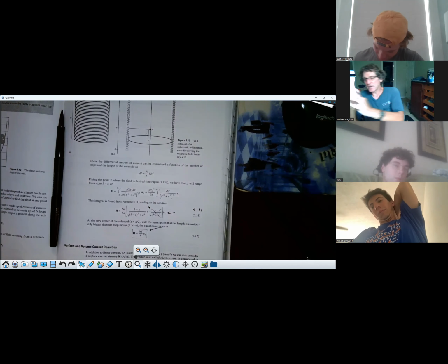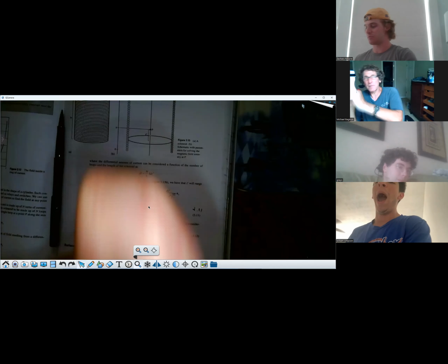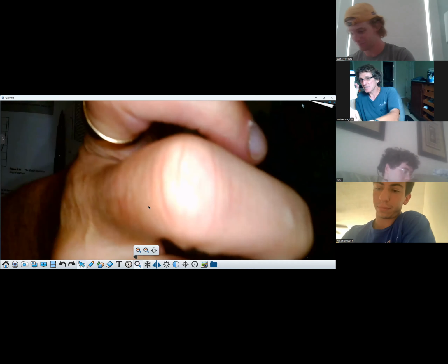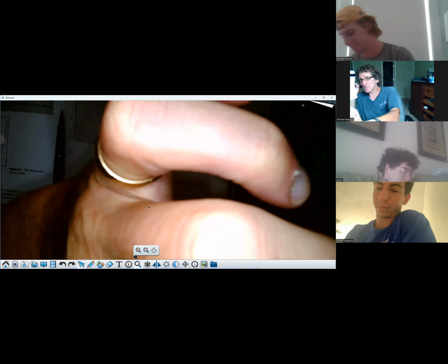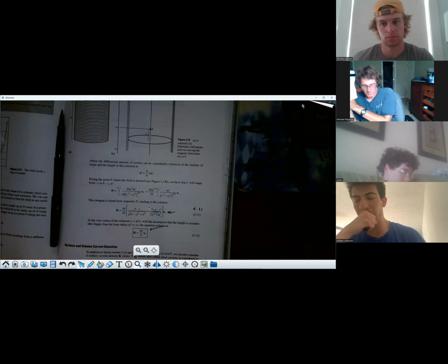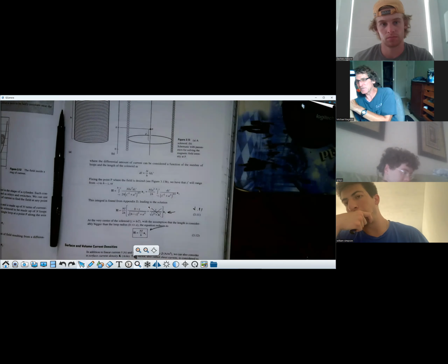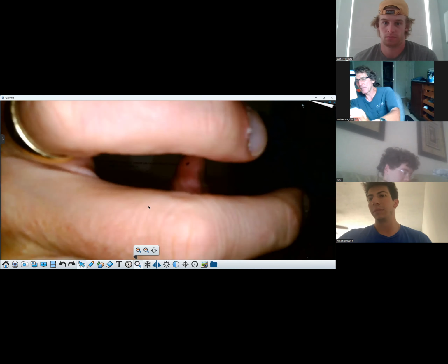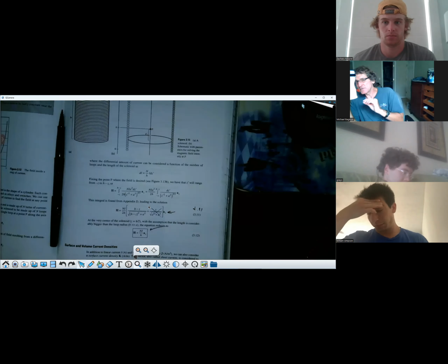So if you just think of something about the size of the core on a roll of toilet paper, or maybe paper towels. So you got something maybe a foot long, and you wind it with maybe 1,000 turns, maybe 10,000 turns of wire. And then you put current through it. It's going to have a magnetic field that's given by this at the center, and it's got a peak value at the center. As you get towards the ends of the coil, and we can prove that, the H field is about 1/2 the value at the center. But here's the one thing about that H field. It's in the Z direction. You all follow me on that, class?